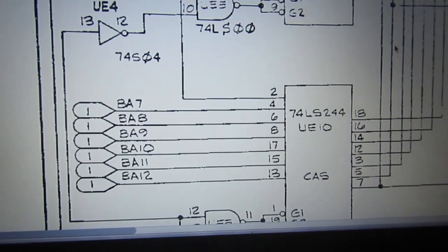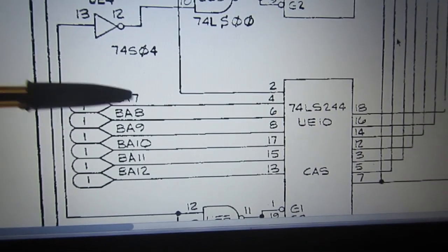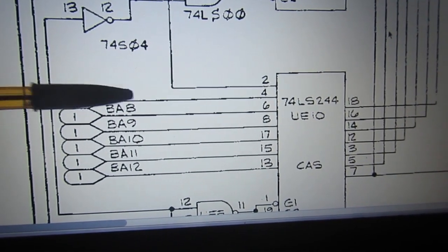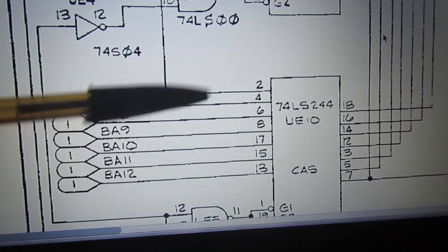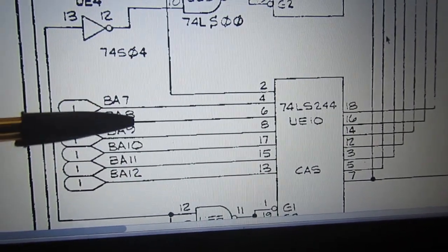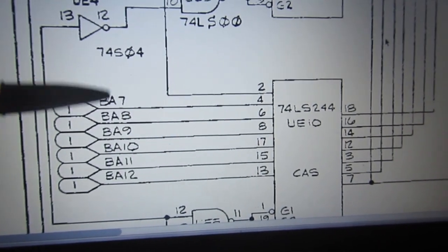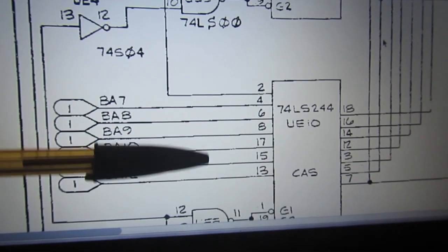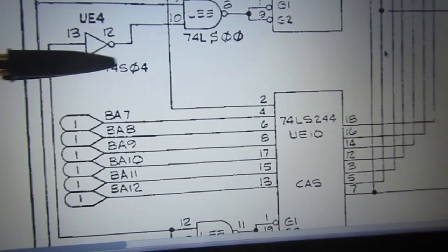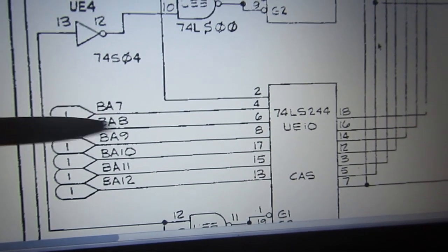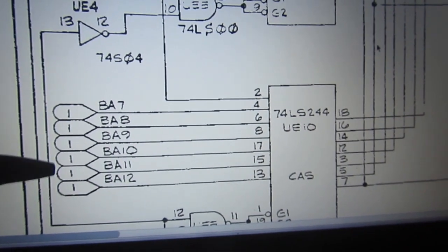So the test filled the screen, the RAM was still functioning correctly, then started to test the page 0, half page 0, the A7 goes to 1, and the RAM starts conflicting the bus, and so everything from this point on starts to get bad, because the CPU cannot correctly see what happens on the data bus bit 0.